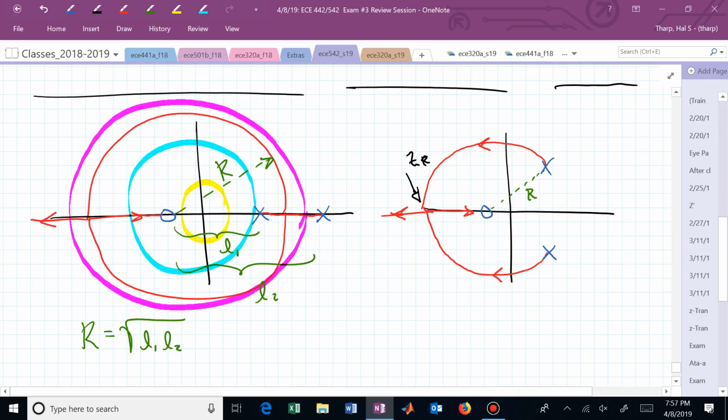That pole, the far right pole, if we crank up the gain K, eventually it will go inside, and the one on the left is still not even to the breakaway point, is it? Which means that this rightmost location right here could be the minimum K for stability. And just assume that this is symmetric in the conjugate sense. Am I stable if I keep K bigger than K min? Am I always stable for K bigger than K min?